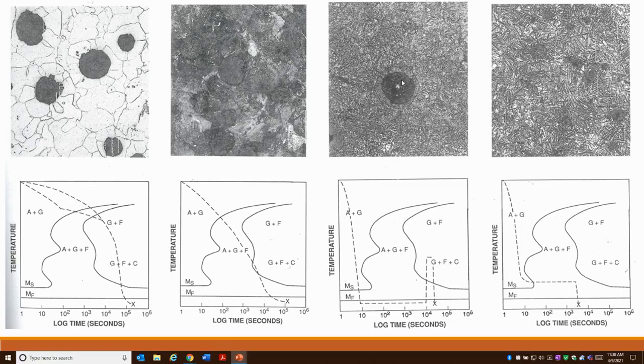So, you know, on the ferritic structure, you have a slow cooling. On the perlitic, you might have a little bit of a faster cooling cycle. And then when you get into the martensitic and austempered, you might actually have to reheat the material to then cool it correctly the way you need to form the correct microstructure.